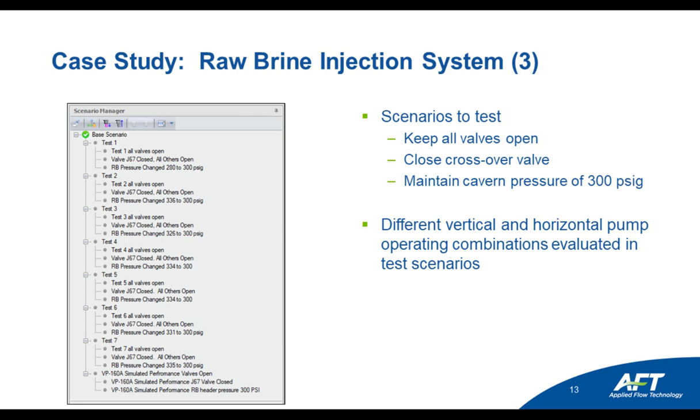This is the entire list of all the scenarios that they ran, and this is critical to finding a good flow analysis tool. If you're looking for a good flow analysis tool, you want to make sure that it has the ability to model any number of operating cases within a single model. And that way you can make any number of changes to input in any scenario,